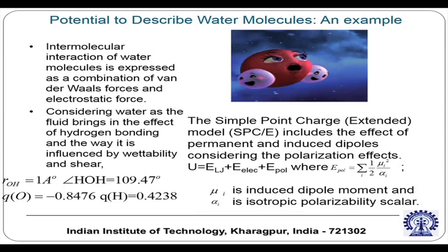Now, in engineering we are many times interested in modeling water through nanochannels. So, how do you represent the interactions in water in a molecular dynamics framework? Intermolecular interaction of water molecules is expressed as a combination of van der Waals force and electrostatic force, and the electrostatic force is very important because water will have a dipolar behavior. So, considering water as the fluid brings in the effect of hydrogen bonding that makes it so special. So, modeling with water is actually not a very simple thing.